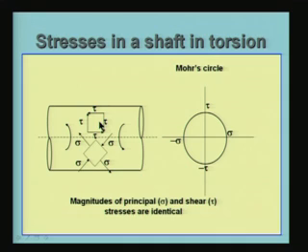In pure shear, when you have a shaft in shear, in fact, you can draw the Mohr circle, which is familiar to you from your applied mechanics. You can see the tau, and the sigma and minus sigma, this is the Mohr circle, and these are the two principal stresses. And you can immediately see what we can do.